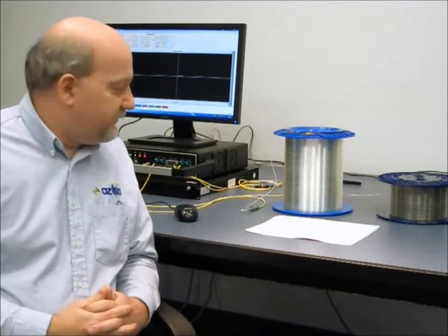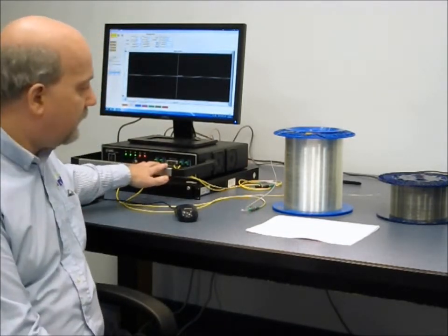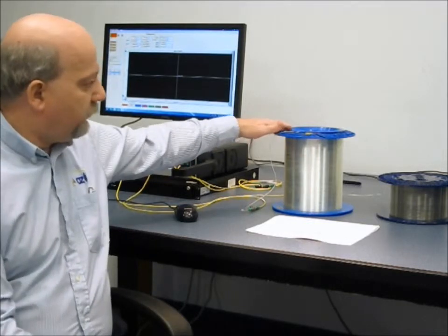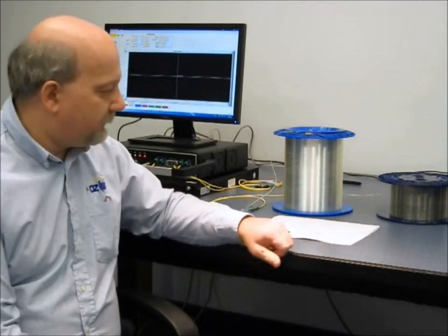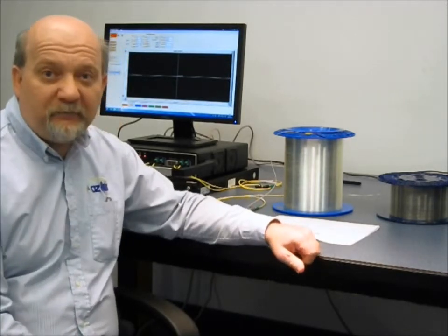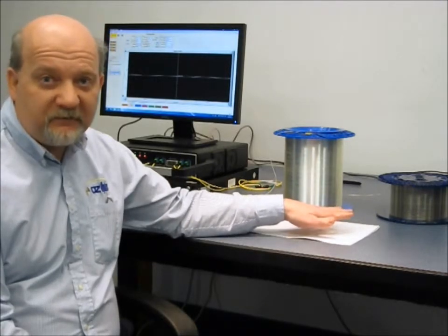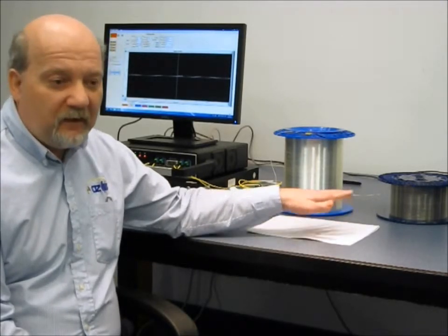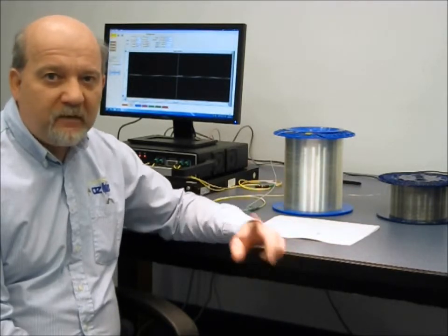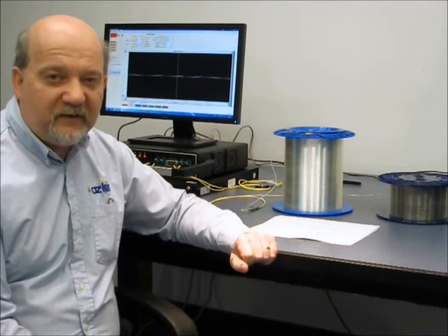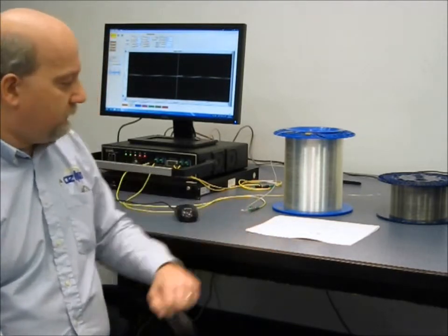So for our demonstration, we have our DSTS system here connected up to 2 spools of fiber, and in between we have a section of fiber. We're going to set up the unit for continuous measurements, and then we're going to heat up this section of the fiber using my hand and have that trigger an alarm on the system. So the first step is to actually set up the software to identify and set alarms.